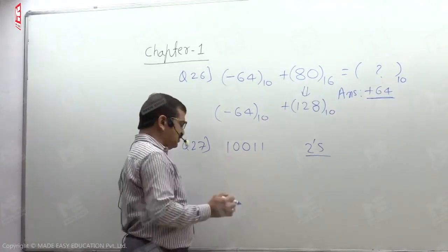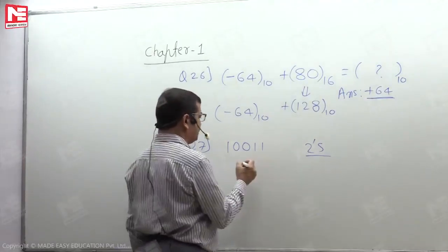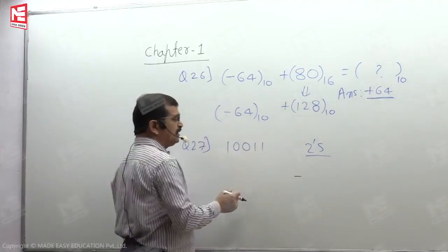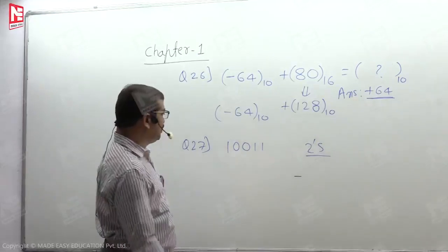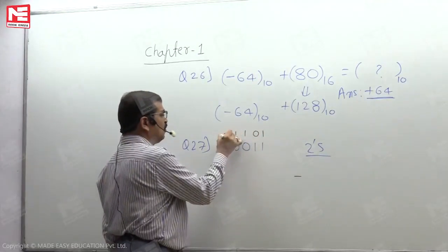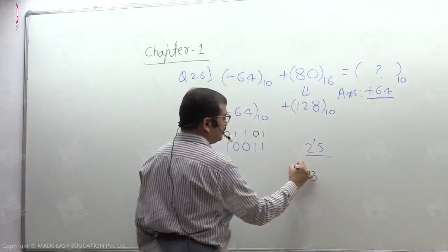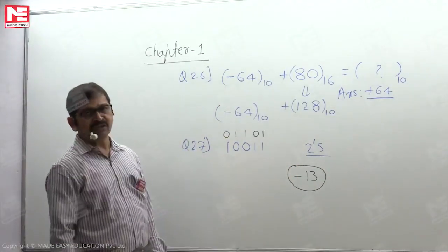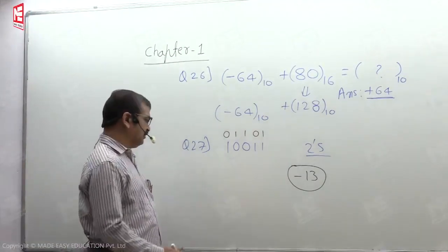While looking at this negative number, one of the procedures I said is, first we write the sign, later to read the magnitude we perform the 2's complement operation on the total content of the register. From this we read its numerical value as 13. Along with the sign bit, it's minus 13. It is one approach I gave.